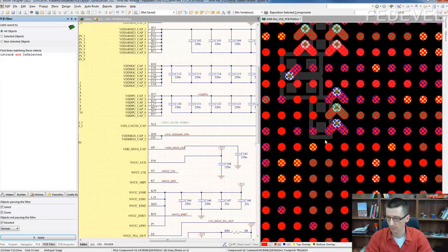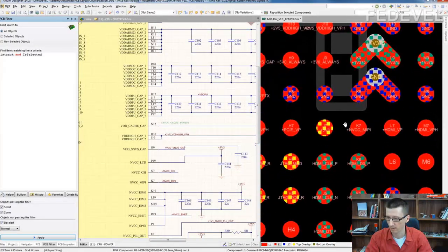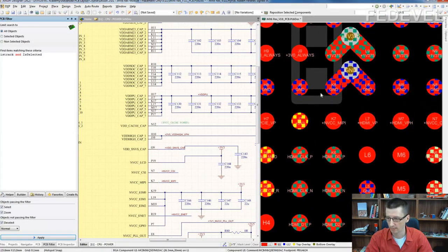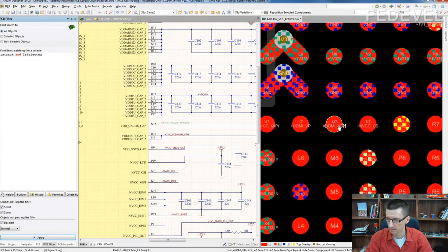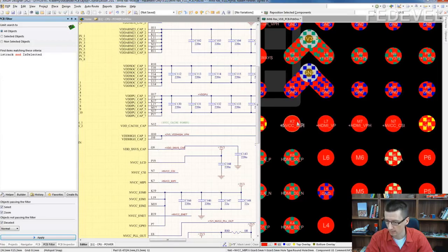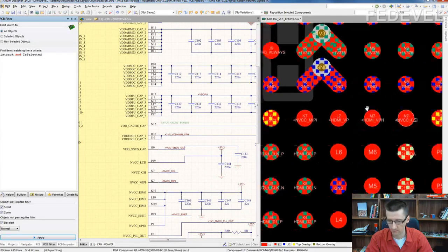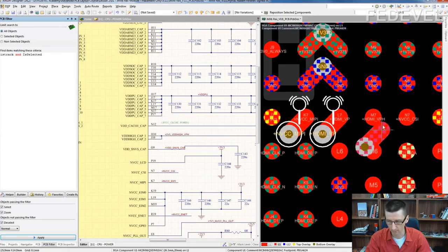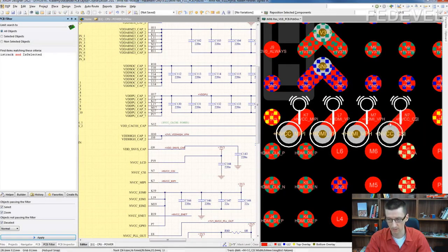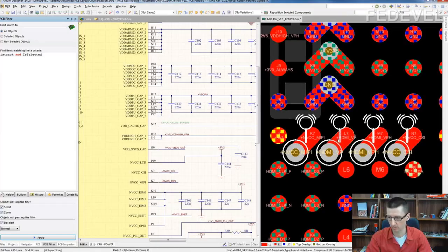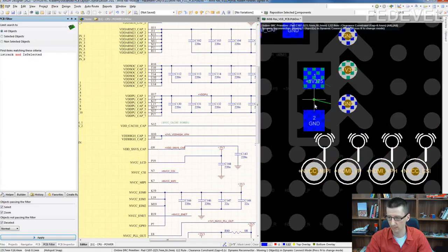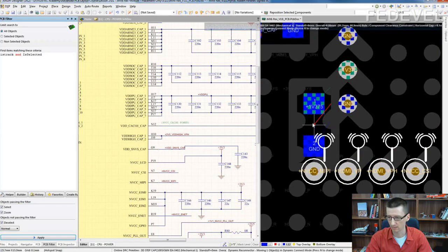What you need to be careful about also is how far you can go with the decoupling capacitors. For example, what I mean, here the pin starts changing. So here each pin is different. This means you need to place a via for each of these pins. Means no decoupling capacitors through this line. So the maximum where we can go with decoupling capacitors is here.